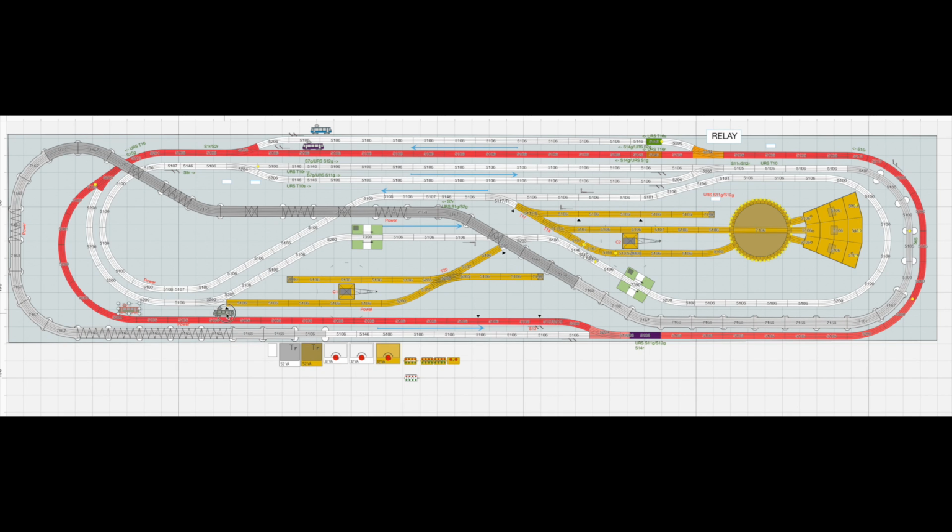The green train has reached the signal and got a green, goes over the switching track. The impulse of current goes back to the relay. It is diverted this time to the active circuit controlling the accessories in the bottom part of the station. So the turnout will be set to straight and the signal to green, releasing the train waiting at this signal.